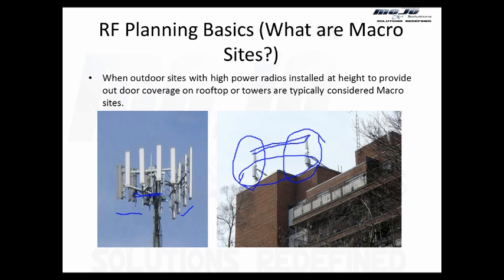Maybe you cannot use a quad pole antenna because it's bigger in size and the site does not allow it, or the owner of the site does not allow you to install those antennas, or the structure cannot support heavier quad pole antennas, so you have to use more antennas. Or there is a load distribution in the structure, there is a frame, so the structural engineer, the civil engineer, or the construction team comes, looks, and says this structure is not approved for this weight of antenna.